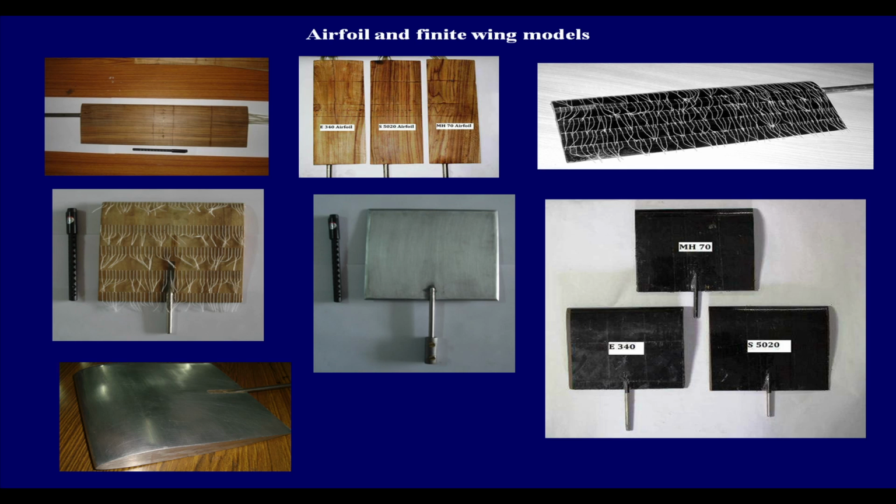So, one way you can be very sure about these things is to go in for a rather critical check, like use something like a coordinate measuring machine, or a similar machine which can measure the coordinates quite accurately and tell you how close or how far you are from the theoretical shape.